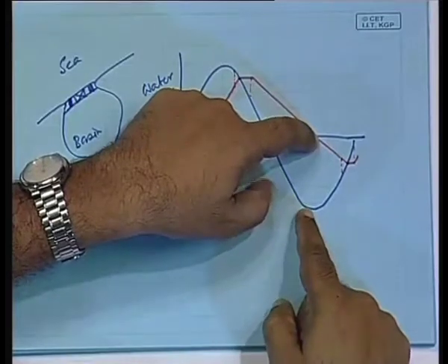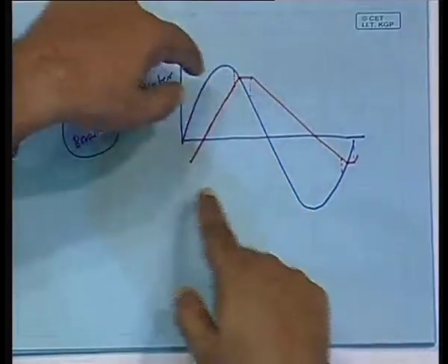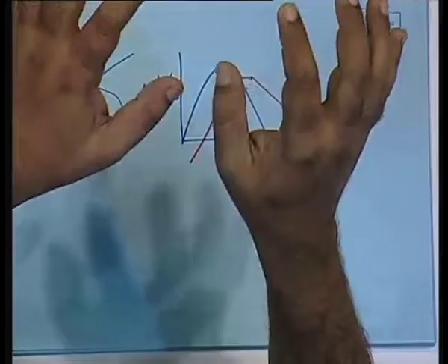Depending on the velocity of flow, that depends a bit on the head. So, when the head is large, there will be a larger amount of water flowing. When the head is small, there will be a smaller amount of water flowing, but nevertheless, the point is that the rate of flow does not depend on whether it is high tide or low tide. The rate of flow depends on the aperture of the turbine and the head difference that you have.